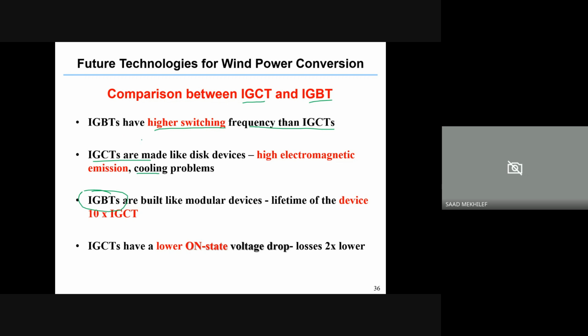Okay, so this is very important because when we calculate the lifespan of wind turbines, we take it based on the lowest lifespan of a component within the system, because there is, for example, a gearbox, a generator, power electronics, and a rotor. So which one is the lowest? That determines the lifespan of the system, because if it fails, the system fails. That's what we call the lifespan, or sometimes the warranty within that time, 10 to 15 years, for example.